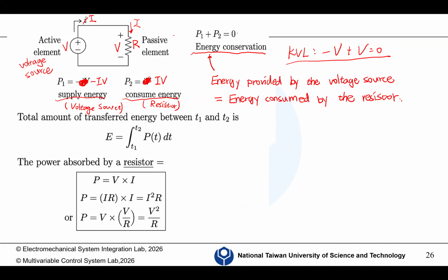If it's a power supply, we say power, and then we know that it is giving energy. Only in the calculation will we say negative power. In reality, we just say power, a positive value. But in the calculation, especially when you are doing homework problems, when it is giving energy, please use a negative value.